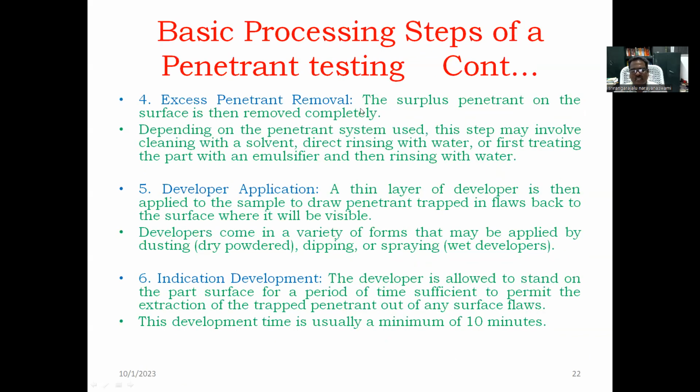And then excess penetrant removal. The surplus penetrant on the surface is then removed completely. Depending on the penetrant system used, this step may involve cleaning with a solvent, direct rinsing with water, or first treating the part with an emulsifier and then rinsing with water.